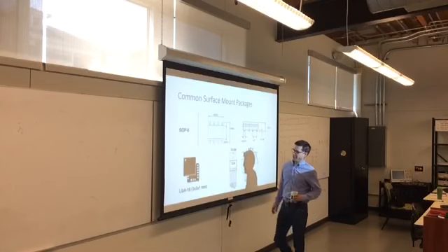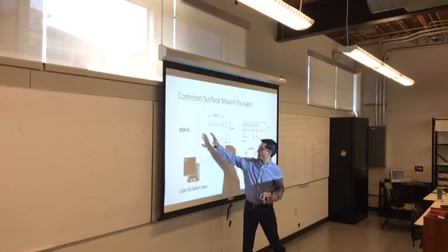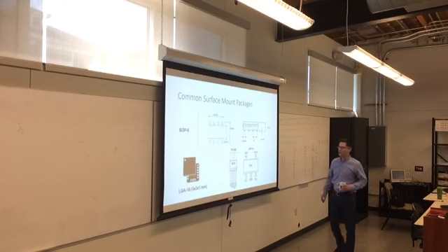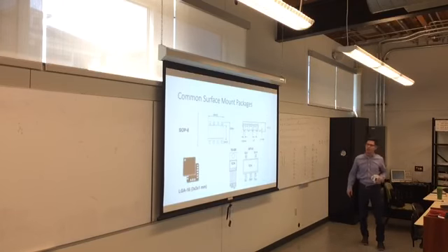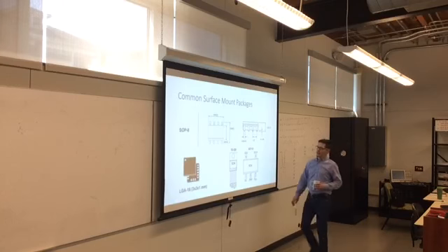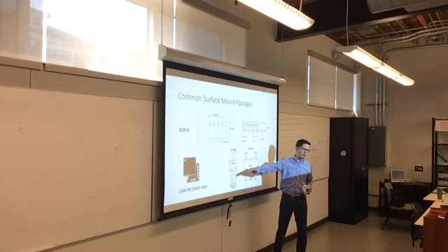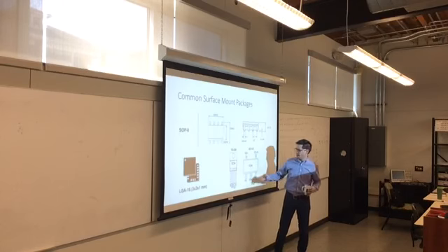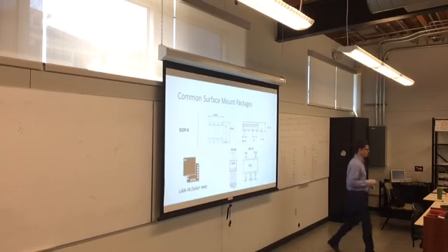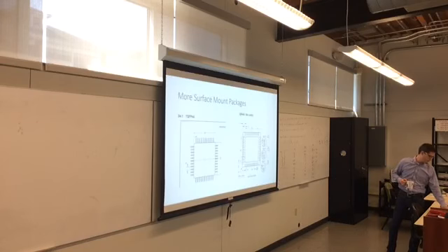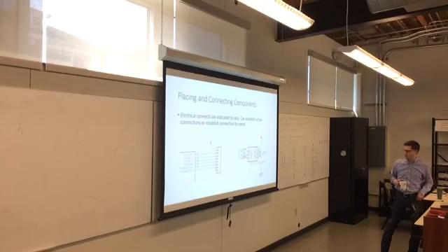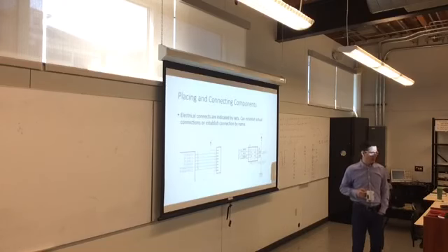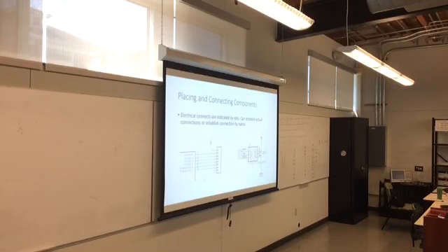Couple other packages, sort of a logic gate array, different pins. You can have sort of different configurations of your different devices. This is a little temperature sensor that we're going to use. If you're going to order it, you can order it in its DIP or through-hole package. You can also order it in your surface mount package. And everything is going to be slightly different, and you can look it up. But everybody's got some sort of package for their parts.